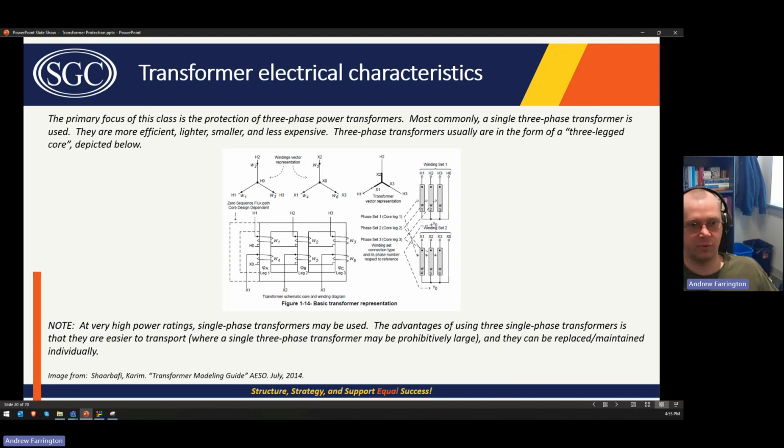The other reason for transformers of that size to be single phase is redundancy, because a transformer that size is probably pretty important to your system. What you can do is put four of them together and connect three of them with your transformer winding configuration made up outside of the transformer tank. Then if one fails, you can reconfigure those connections, whether it's reattaching new bus work, or maybe it's already connected and you just have to close some switches to swap it out.